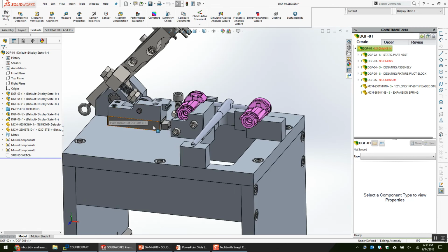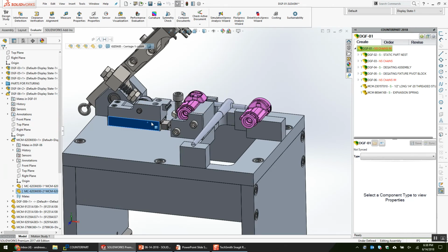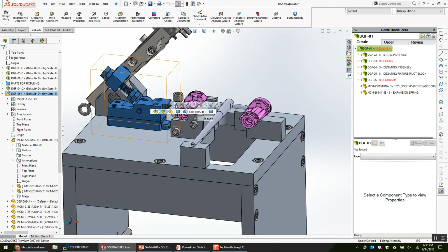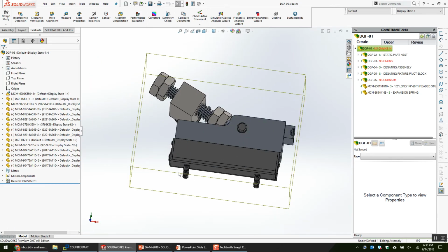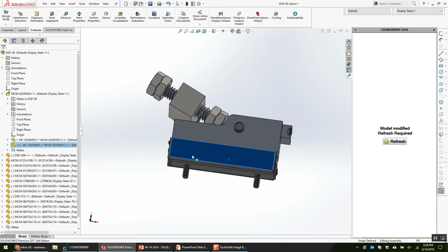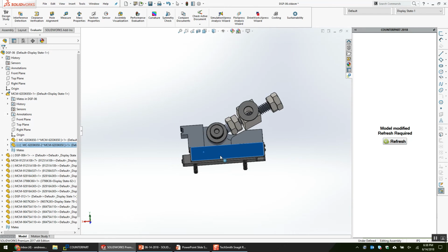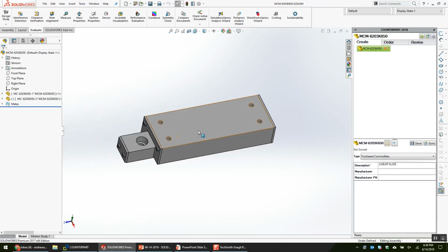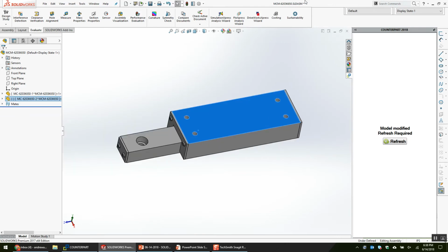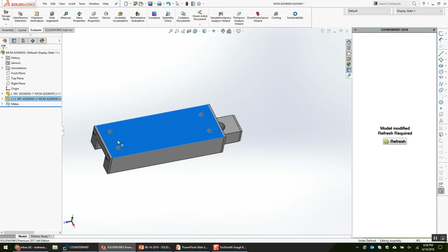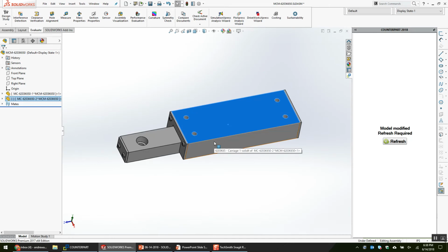So here inside of SOLIDWORKS, I have a subassembly that is a linear slide that looks like so. And we'll look more at the main assembly and what we're actually trying to accomplish. But we got this slide. So when I download this from McMaster-Carr, I really want two independent part files on my hard drive so that I can animate, kinematically move that slide.